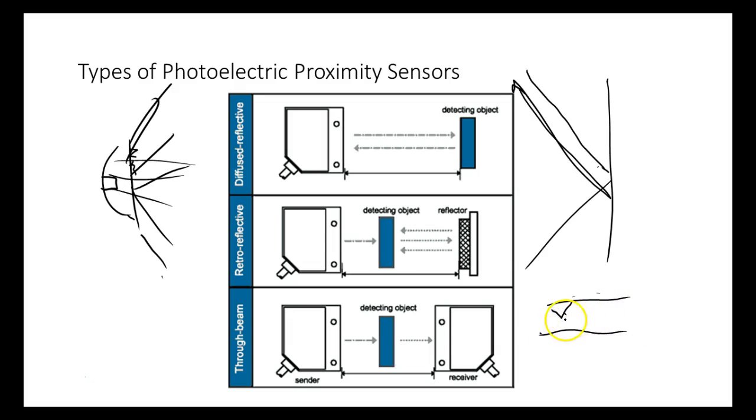It'll transmit and hit the object, and if the object is at the right distance, it'll bounce back up and hit the receiver. If the object is not at the same distance, it's either going to miss the receiver over here, or miss the receiver over there. So definite reflectives basically sense a device or something that's at a precise distance or close to it.